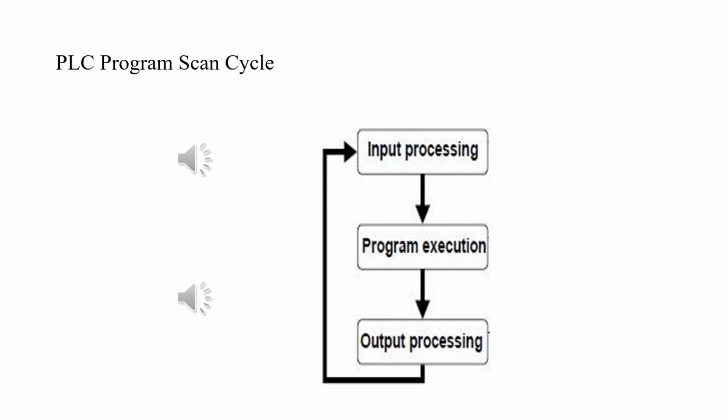So changes occurring on the input devices after the input processing phase is finished will not be reacted upon or felt until the input processing phase of the next program scan cycle. And as I said, the time for changing inputs is much longer than the program scan cycle, which is in the order of 50 to 100 milliseconds, and the change of inputs may last for 200 or 300 milliseconds.